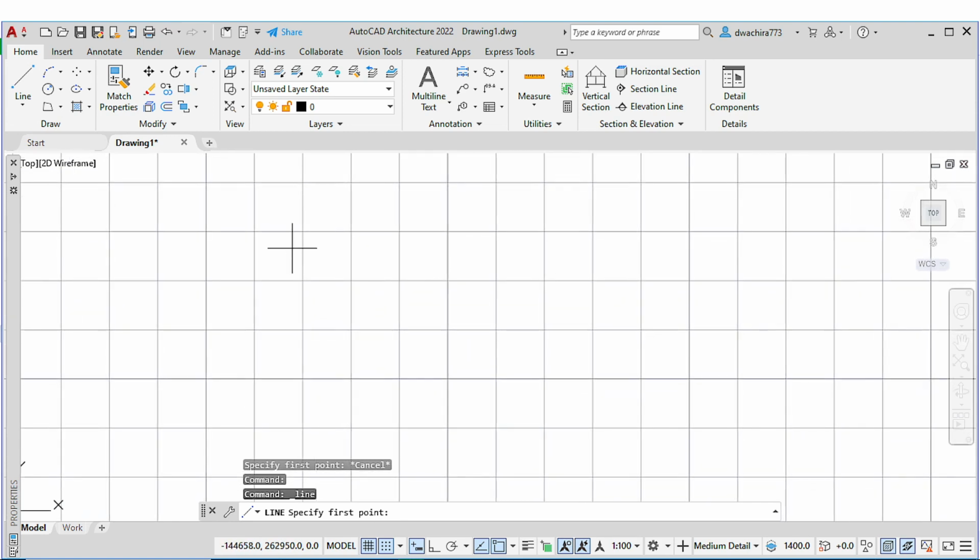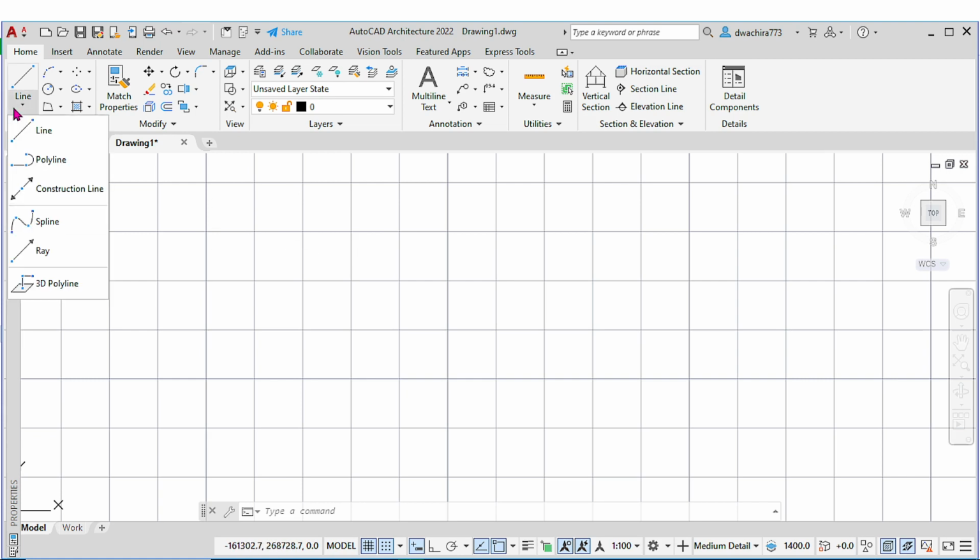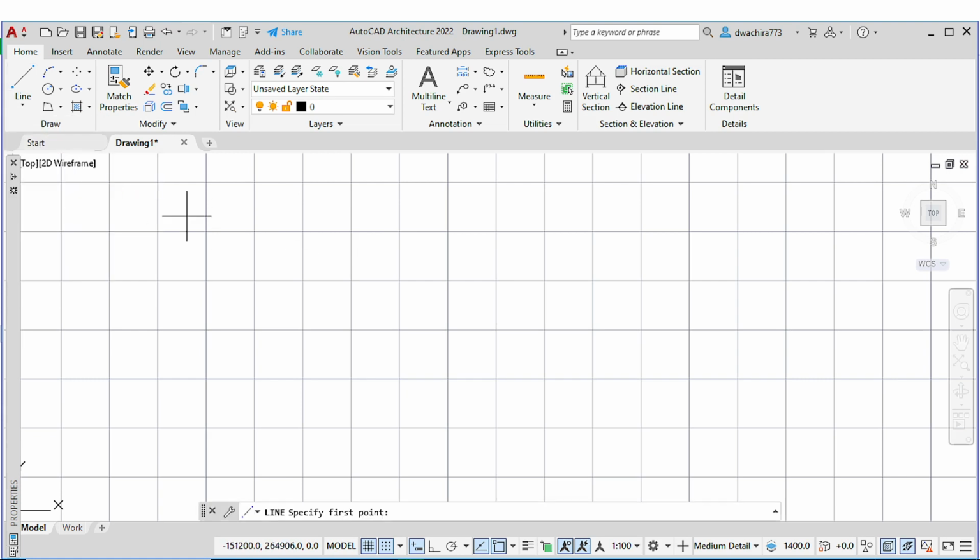And you should note that once an object is active, your crosshair is going to have that kind of symbol. But of course, if for example I press escape, if an object is not active at all, then the crosshair is going to have that particular square at the center or at the intersection. So note the two modes. This mode that you can see currently is called the selection mode, and once you activate an object, then you are going to have the input mode or the drawing mode, where you can now proceed and draw the object that you have activated. So with the line work, I can now proceed and start placing.